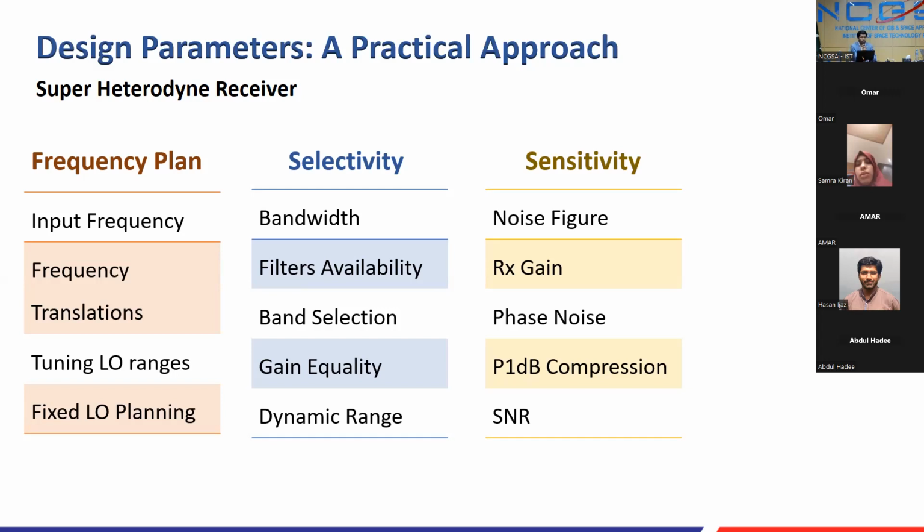Gain equalization is, for instance, on your ADC, in one of the systems we are working on. When the signal is received, we are more interested in the amplitude of the system. The frequency aspect we are not interested in. So let's assume that the signal's bandwidth is around 4 to 10 gigahertz. When this much bandwidth signal will be sampled by the ADC, you need a uniform envelope of the signal. You don't want upside-down ripples or fallings in the signal, because your ADC will, at one time, be sampling 0.1 volts, 1.2 volts, 0.8 volts, 0.2. The actual signal incident on your antenna might be of uniform amplitude. So that is the non-linearities or the discrepancies added to the signal by your receiver. That parameter is known as gain equalization or gain flatness.